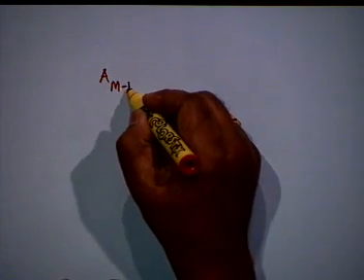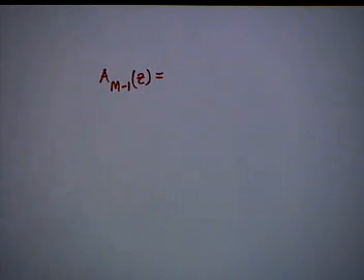The next step is to find a lower order all pass, order less by 1, by using the relationship: we form a transfer function one order less, A_(m-1)(z).